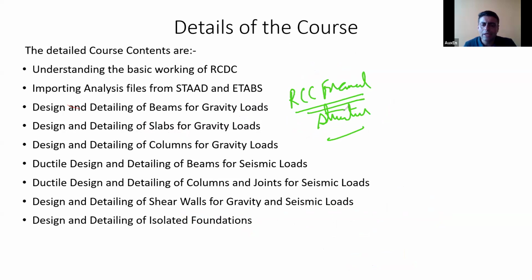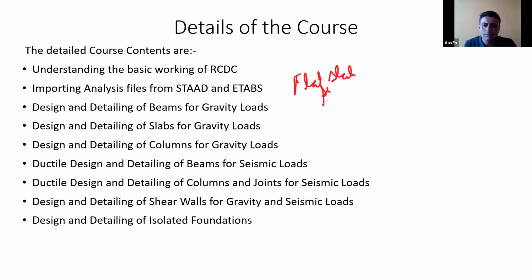Otherwise, you may have a flat slab system or any system, whatever you are doing. You can just do the beams and columns over here. And for slabs, you can use a different product like ETABS or SAFE. So if you have a flat slab system, you can do the beams, columns, and walls, RCC structural walls, in RCDC. And for slabs, you can use SAFE or any other such software.